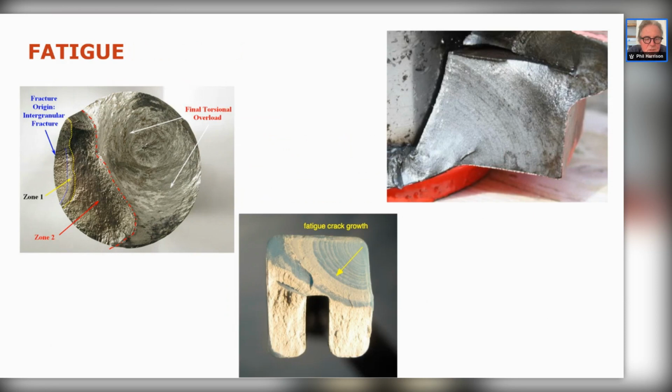The logic behind this is that if you have a material that's not tough, that can undergo brittle failure, once you initiate a fracture, a crack in this, for example, through fatigue, it can actually propagate straight through the material. So you can see on this where the crack is actually initiated from and where it's moved through the material.